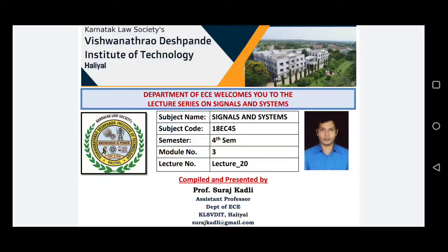In the previous video lecture, we understood the relationship between impulse response and four of the system properties. For an LTI system to be a memoryless system, its impulse response should be a constant, represented by the form: for a discrete LTI system, impulse response h of n should be of the form c delta n, and for a continuous LTI system, impulse response h of t should be of the form c delta t. Then only an LTI system will be a memoryless system.